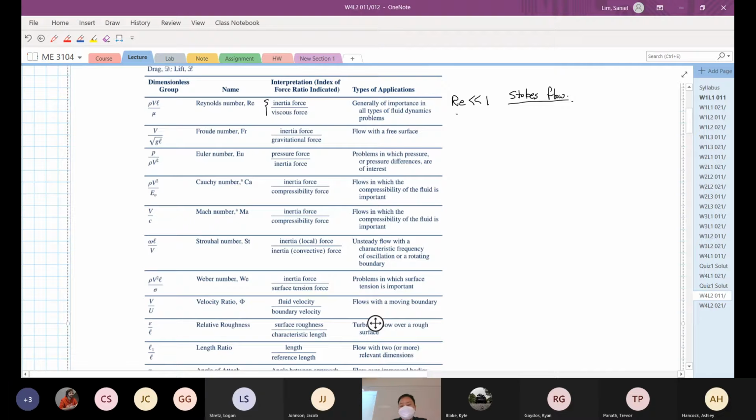All right, if the Reynolds number is larger than a certain number, I didn't say any specific number here. If it's pipe flow, it's going to be around 4,000. If it's the open end, the horizontal plate, it's going to be 20,000 to 50,000 Reynolds number.